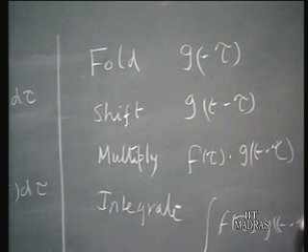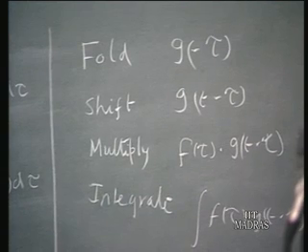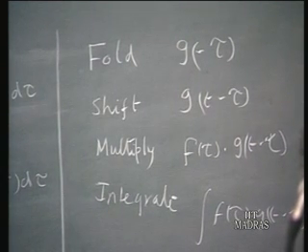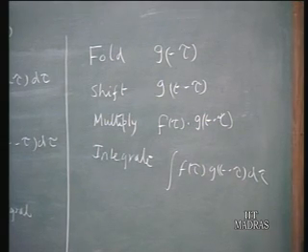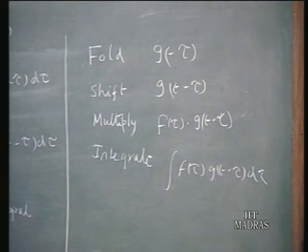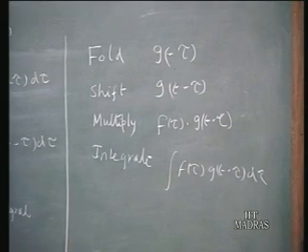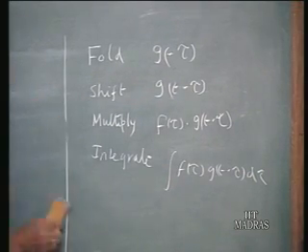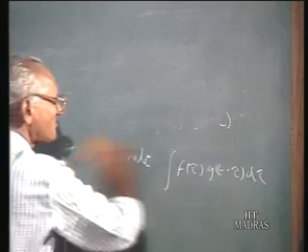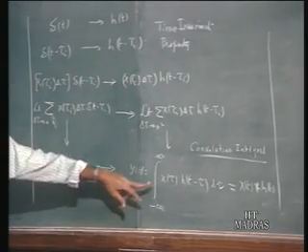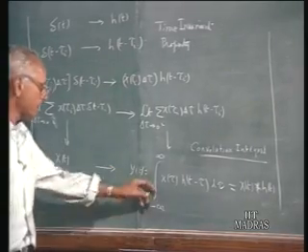If you keep this at the back of your mind, we can find out the convolution of simple functions quite easily without going to the mathematics. From the physical graphical approach, you can find out the convolution of different functions very easily. Now, let us look at these limits. This is the general expression for the response y of t for any given x of t.